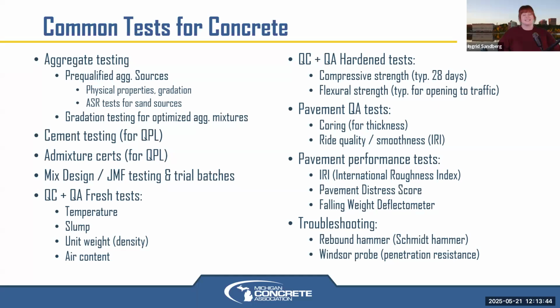We have a question here, Ingrid. Yes. So this question is about that kind of post-construction testing. This individual has an 8-inch concrete slab acting as a brick paver subbase, and they've had some sporadic crumbling in the upper 2 or 3 inches. The pavement is fairly old, 20 to 30 years old. They're wondering what kind of tests might tell them how deep that damage might go, and if it would be appropriate to do a mill and then bond coat and top that off versus having to replace all 8 inches. Is there anything that could tell you how far that damage would extend?